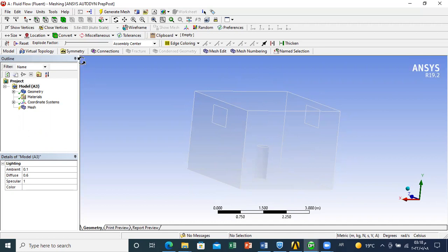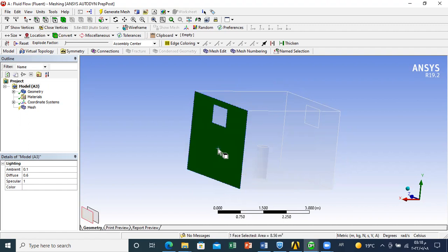To do this, first you select this tool. This tool is for selection of a face. Okay, so I can start with naming my parts. Now, here, for example, we have 4 walls. You might say that if all walls will have the same condition, so you have same heat flux through all of the walls, no need to name wall 1, wall 2, wall 3, wall 4. Because at the end, if there is no difference between walls, I can select the 4 walls. In case, let's say, this is an internal office, and all of these walls are partitions, maybe you can consider then that the heat flux is nearly 0, so it's a good strategy to select all of them. In case each wall is subjected to a different condition, you need to name them separately.